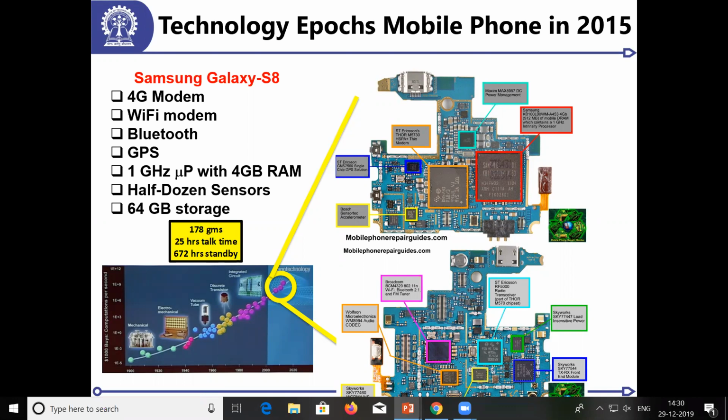It will receive close to minus 98 dBm of signal. Minus 98 dBm is probably a few microvolts of signal, right? Now that microvolt of signal has to be received and it has to display a picture, right? So that means your accuracy of the analog signal. If it is let's say 64 microvolts, and if some large switching happens, then that 64 microvolt becomes 256 microvolt, the bit flips. So you will have all kinds of problems when you are in a receiver or something.